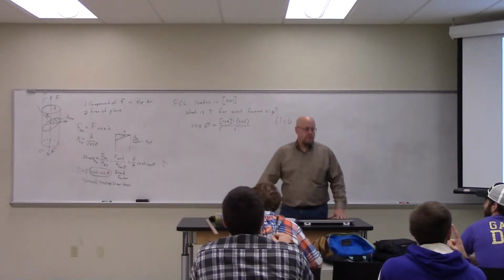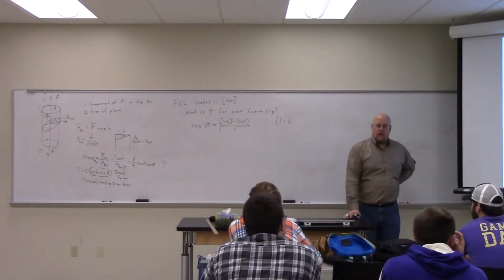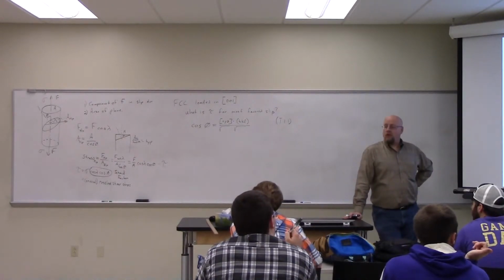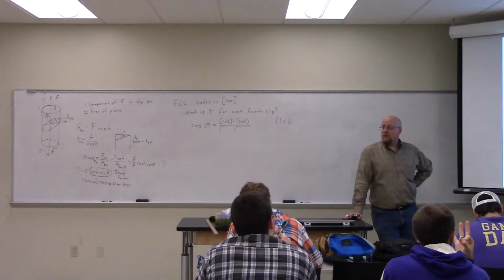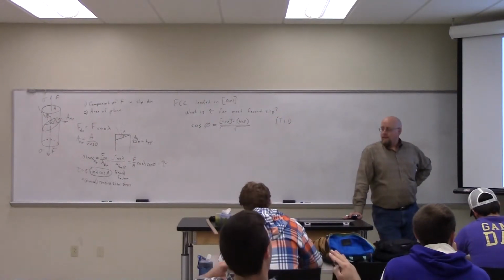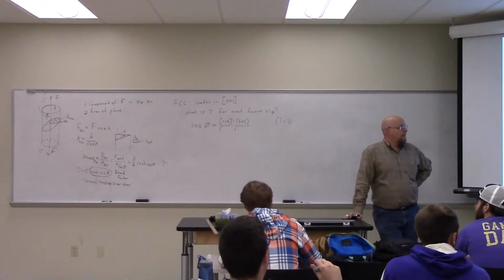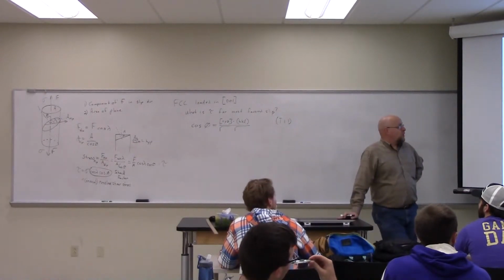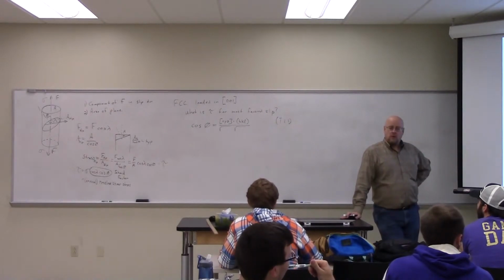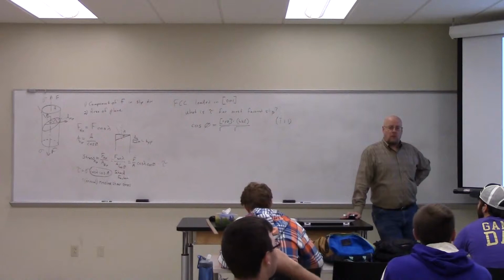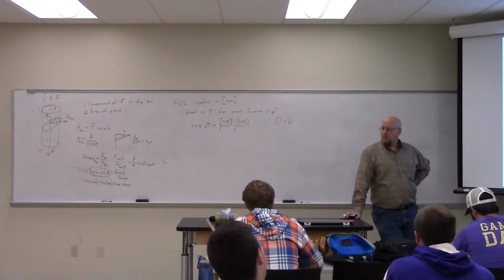How many directions are there per plane in FCC? 3. Which ones are going to be active? The two that have a vertical or a Z component. So really only those 2. That third one along the bottom, I'm pulling perpendicular to that direction, so I'm not going to get anything to slide that way.